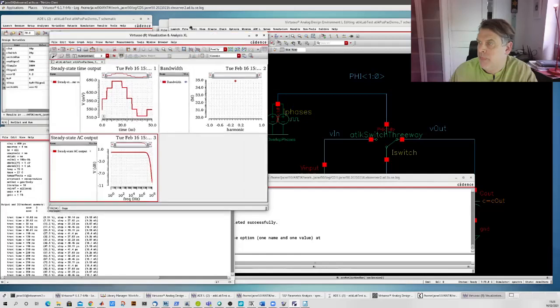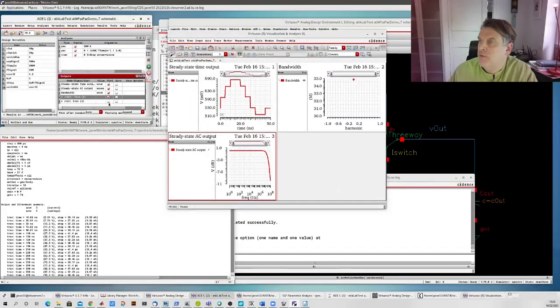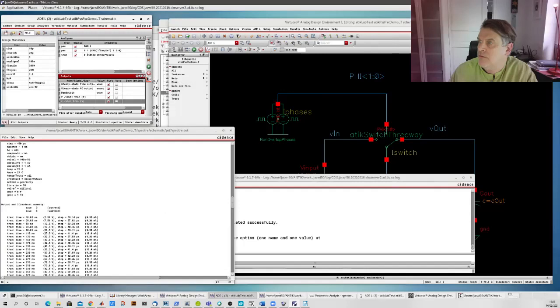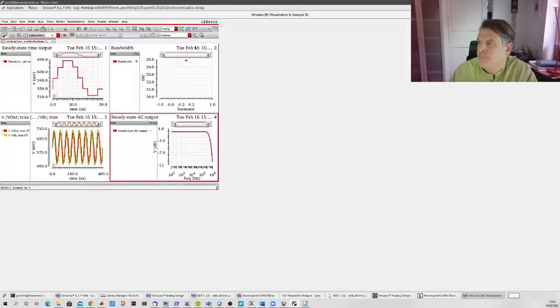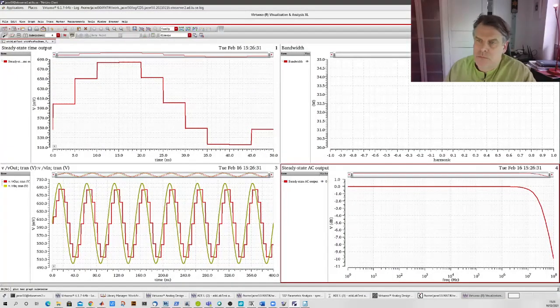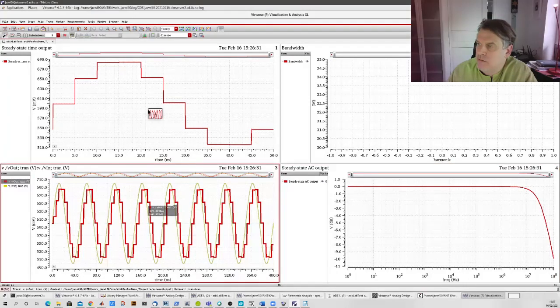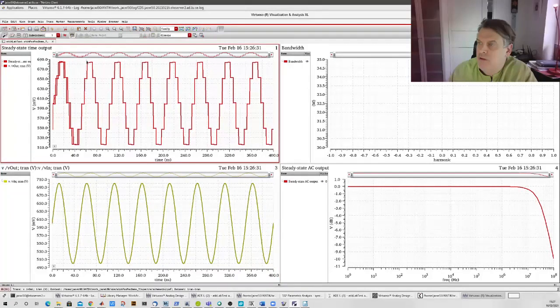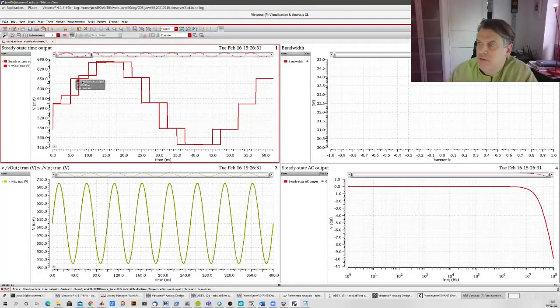All right, so now we can also perhaps plot the transient curves also. There we are. Okay, so this is my transient analysis that we did. This is the result from the PSS, periodic steady state. So it has found the sampling behavior that it expects on the signal. So we can, for example, compare that with our transient simulation, and we see that they are more or less on top of each other.